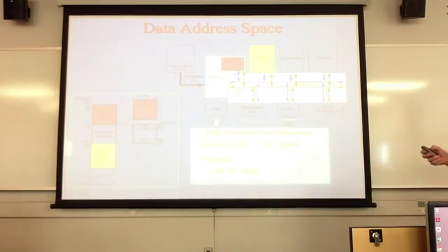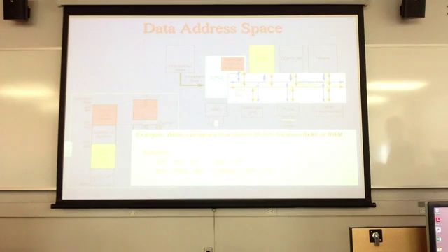All right, so what we were doing is we just did some loads the other day. You did some loads today. And simply, storing to data space, you just give it an address and a register. So if I just took the contents of register 15 and wrote it to memory location 060, it just takes that and stores it up there. Writing a 55 into a memory location: again, just put it into a general purpose register, and then take that register's contents and write it to a physical memory address.